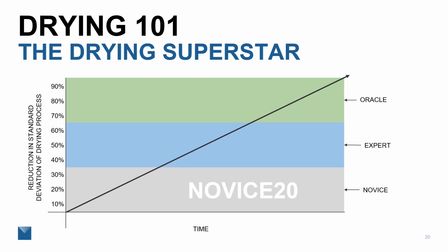Here's how it works. Once you have the system set up on the iPad, you click on the name of the product you're testing. Then every time you take a water activity, it's written permanently to the batch record. One user was able to track their continuous oven in near real time and significantly reduced variability just by making this data visible to operators in her factory.